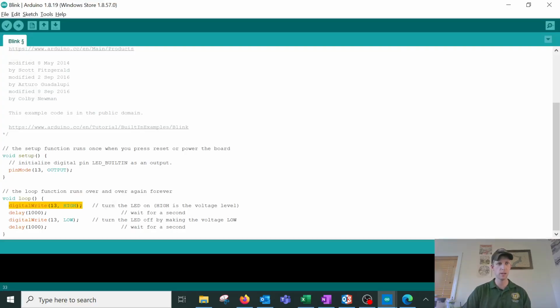So let me modify this piece of code right here. I'm going to tell the Arduino IDE that, instead of calling digital write, what we're going to do is tell it, hey, take 25, treat it like a pointer to an 8-bit integer, and give the value at that memory address a 1 left shifted by a 5.